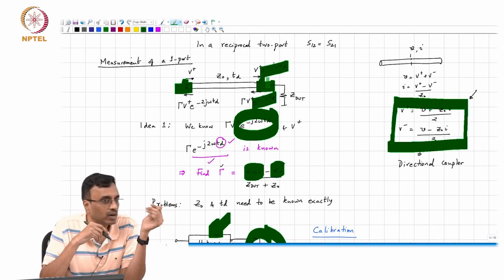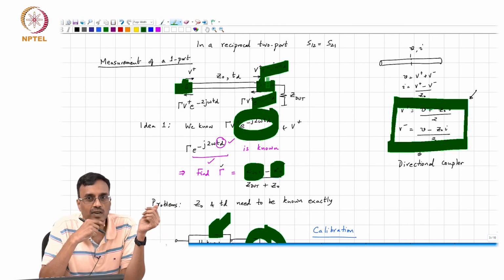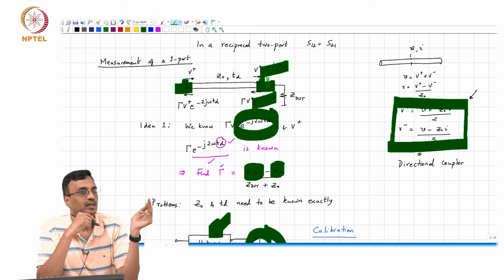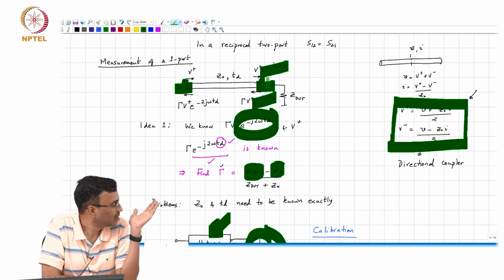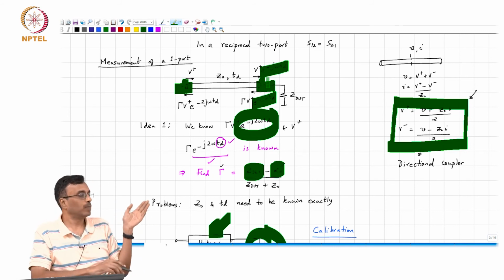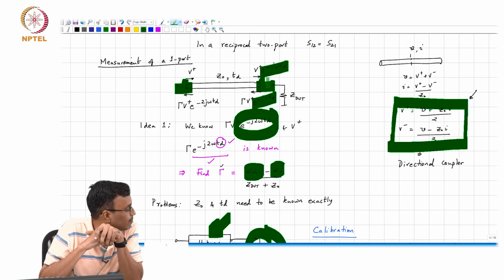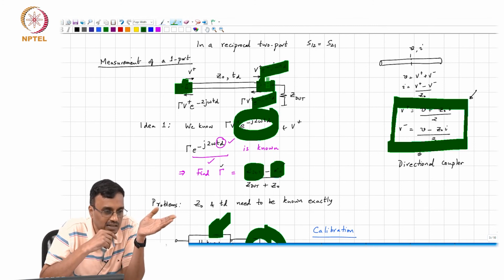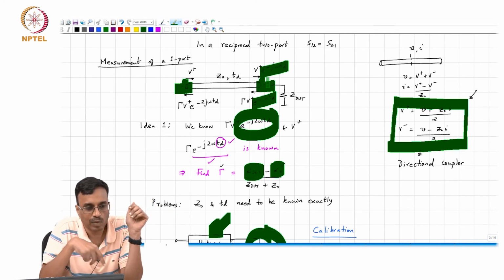So 20 nanoseconds times a gigahertz times 2 pi means that e to the minus j omega Td is a significant phase shift. It's not 1. As you can see, omega times Td at a gigahertz is several multiples of 2 pi.